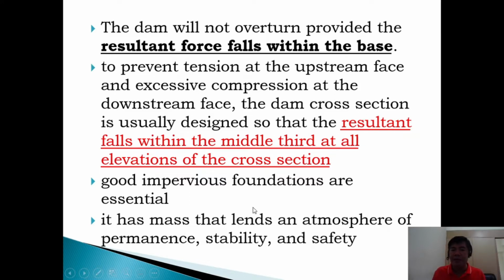Good impervious foundations are essential. Of course, here we are looking only into the analysis of slope stability. But in the total design of a dam, the design of the foundation should always be considered, because, as we know, the foundation carries the total structure above it.